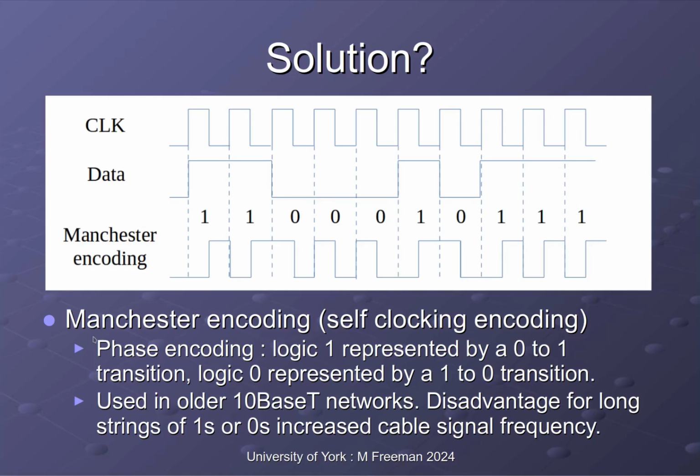And if we dive too deeply into the electronics, you also have a problem with DC bias. So our cable will have resistance, capacitance and inductance associated with it. And effectively what that means is that you can charge up the voltage on that cable. So you can see here, this is what the signal may look like on the transmitting end. But you can imagine those voltage pulses that we're driving onto the wire will charge up that capacitance in that wire. So what that will mean is that at the other end of that cable, you don't discharge the voltage on the cable back down to zero. There'll be some standing voltage on that cable.